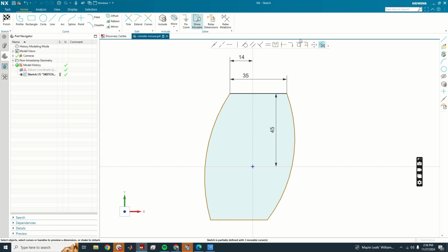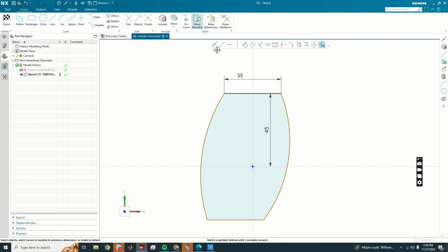So basically, I'm going to leave this on now, delete that, and now I'm going to make a new constraint between this point and midpoint, make coincidence. There we go. So now it's snapped there, and if I try again to make a new sketch, it's really obvious when I do this that I'm breaking that relation that I previously made, but sometimes it's not always obvious.